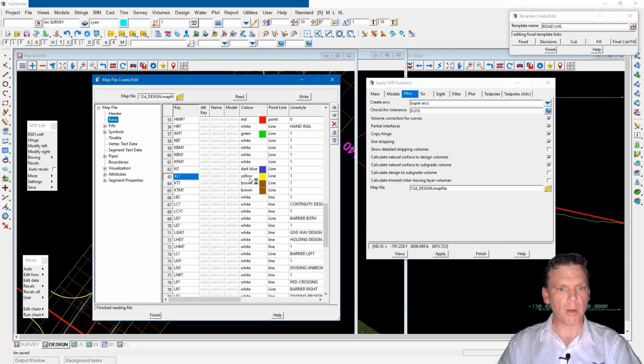So curb lip line, it will turn those strings to being yellow. And if I wanted to, I could also apply some sort of a line style to them if I've got some sort of a line style that I wanted to apply there. Now the little question mark obviously is to replace the letter L and R. So that way this KL, if it's left, right, or anything else, as long as the string is named correctly with KL, it will get colored up yellow for me.